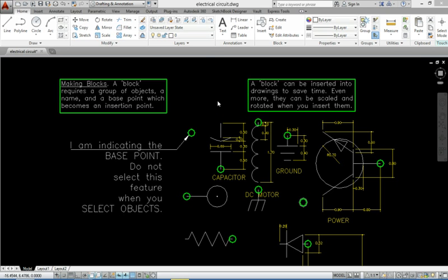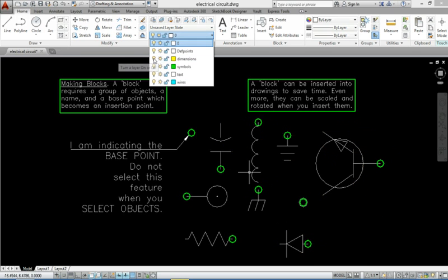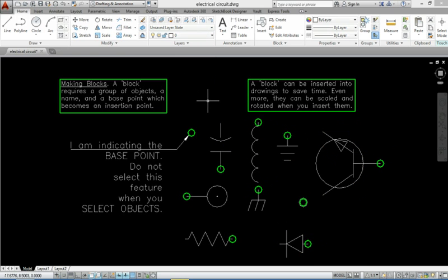In order to make your assignment, I had to use layers. So you'll see layers when I hit this down arrow. However, when you make blocks, you only work on layer 0. There should be no other layers in this file at all. Let me take off the dimensions so that we can begin.